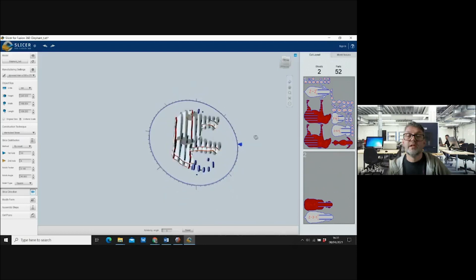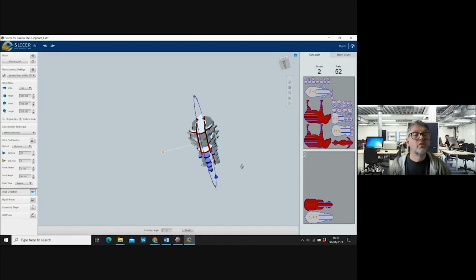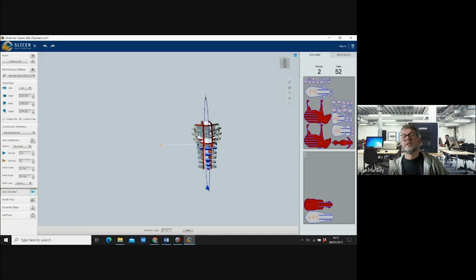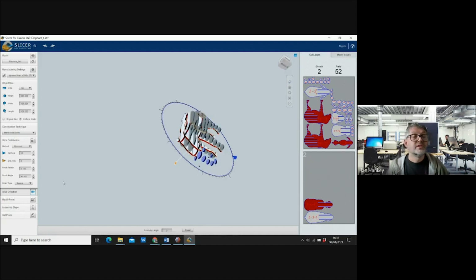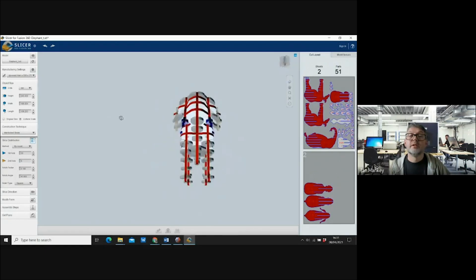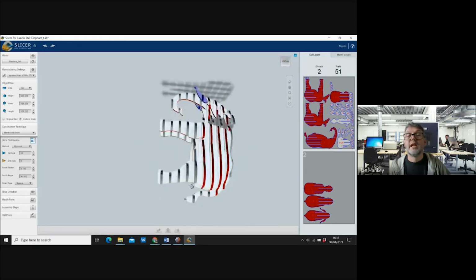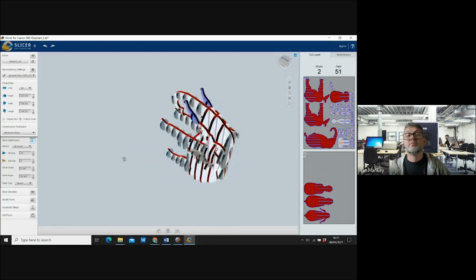And that's not working either, because can you see I haven't got a central section. So looking at my axis number, I can see at the moment there's only 4. I think my axis running down is going to have to be odd. So I've got one in the middle, which will hold my trunk together. So let's just see what happens when we make that 5. Now I've got my trunk in the middle, and all of a sudden it makes more sense. We can see that everything except for the tusks is working.